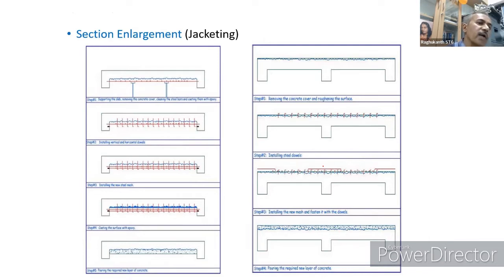As I already told you, for most of the structures we have done all kinds of tests, like half cell potential, all kinds of things to identify the causes, and it took a lot of time. We have also made some mistakes. Some cracks, we said, were due to corrosion. But when we did the test, there was no corrosion. It was some flexural crack or a shear crack. So many issues are there. It is not that straightforward.